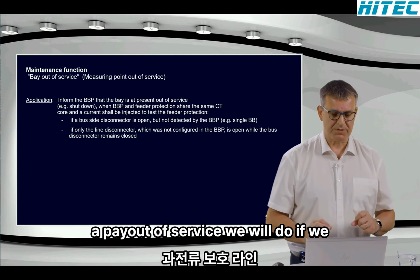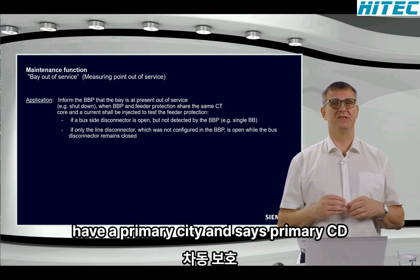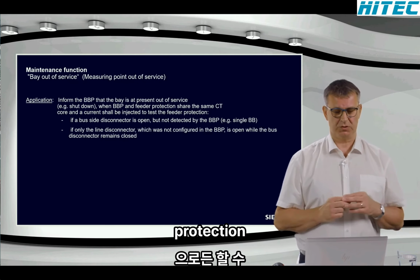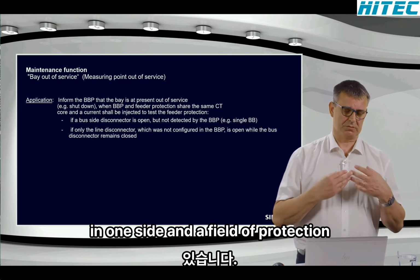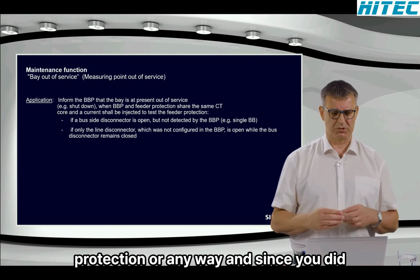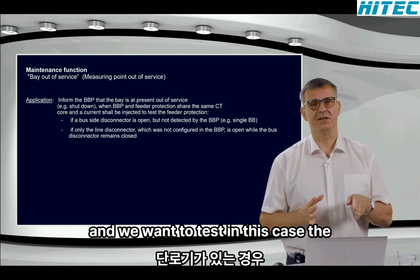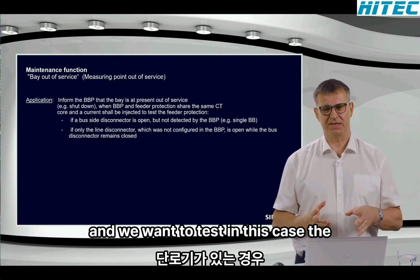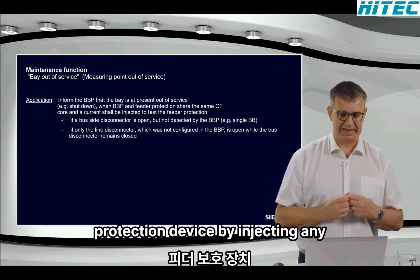A bay out of service we will do if we have a primary CT, and this primary CT is shared between the busbar protection at one side and a feeder protection. Anyhow, it could be an overcurrent protection, a line differential protection, or anything. And this CT is shared. And we want to test, in this case, the feeder protection device, the line protection device, by injecting any current.